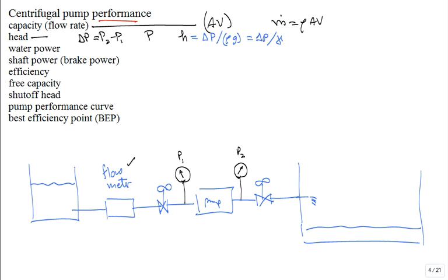It's the weight density. So, okay, sometimes they'll also put it in cap H, little different head. That head is energy per unit mass. Well, you can jump always between these things. So it's delta P divided by what? Rho? Isn't it? If this is energy per... So I know that a lot of times we talk head, and we talk head in units of feet or meters. But sometimes you'll see a plot of pump performance and its energy per unit mass, or its pressure.